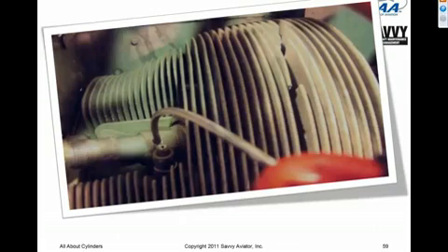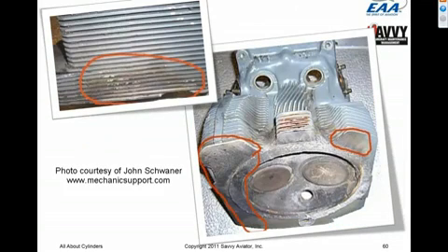Here's one that was getting ready to separate but didn't completely come free. Here's a Lycoming cylinder that had a complete separation. Something that's really important to understand is that these aluminum cylinder heads have a finite fatigue life.